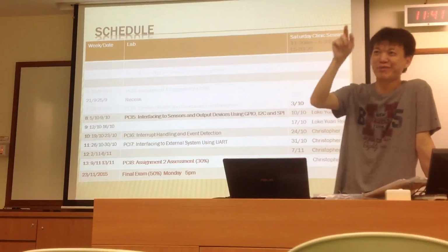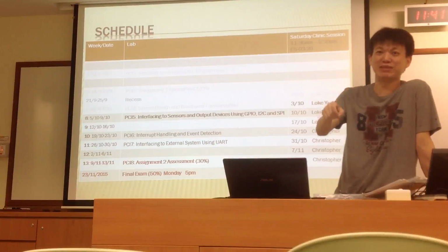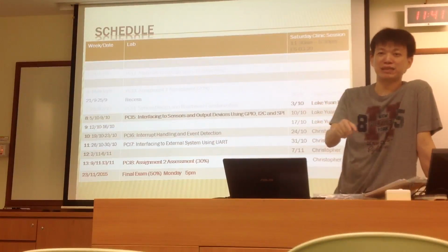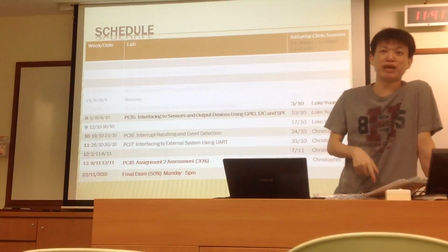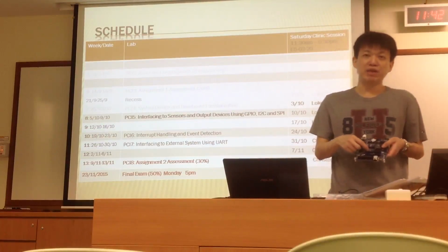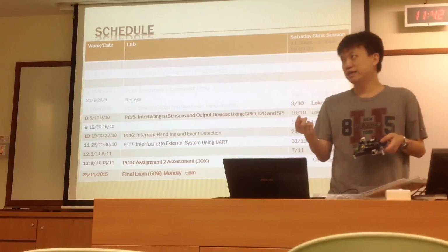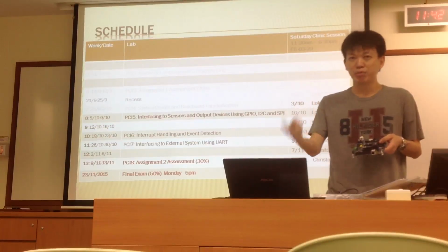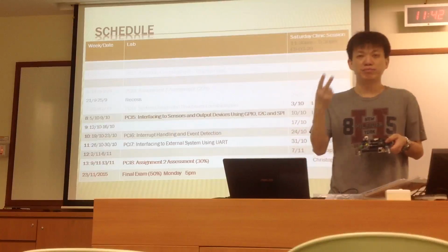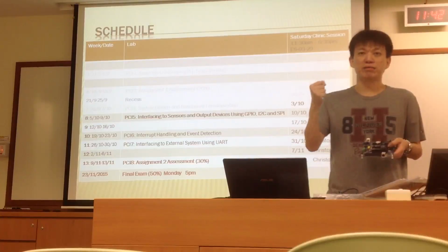Actually, if you go back and comment it out, you find that it's still working, because the default setting is 0. All the default settings are 0. The function number, if you didn't write a setting in GPIO, is 0. So implied, any pin that you didn't configure, its default setting is always 0. It's always the GPIO setting. And then pin function, pin mode: if you didn't set anything, pin mode default setting is 0. Implied, all are pull-up.